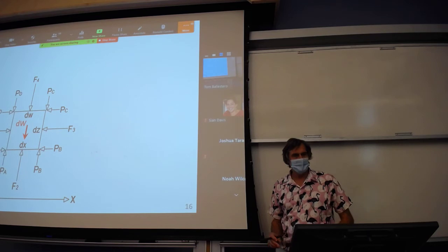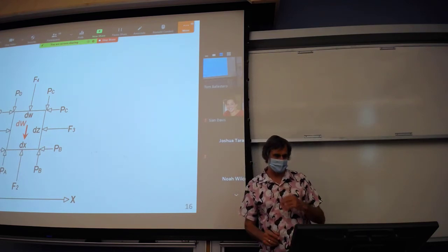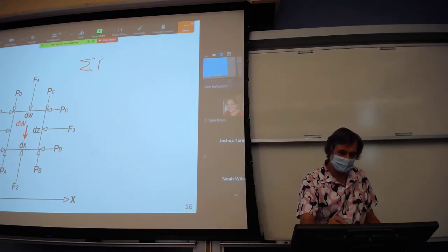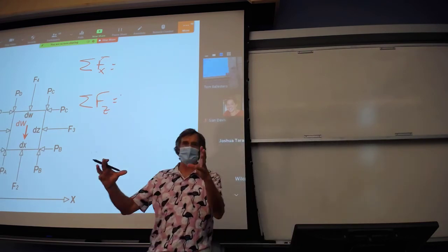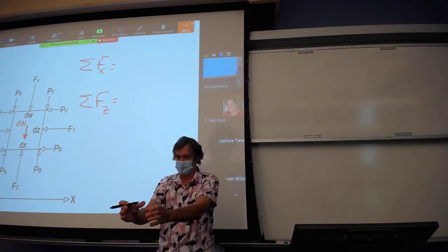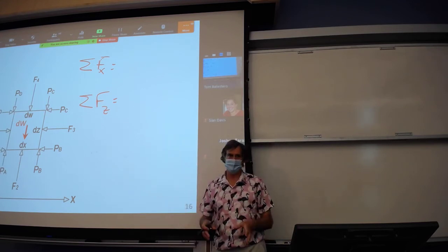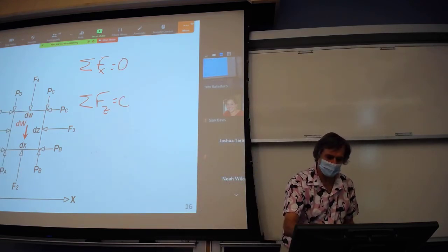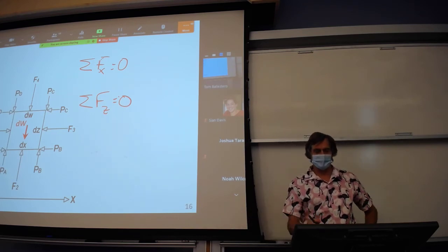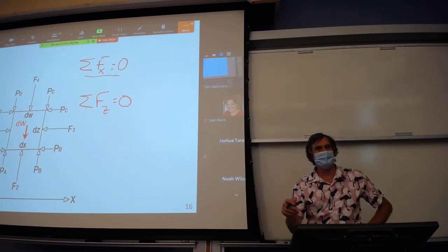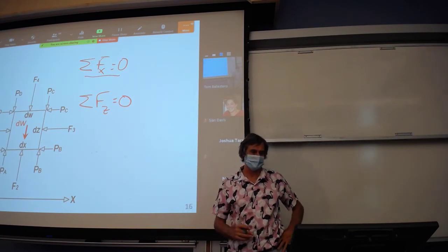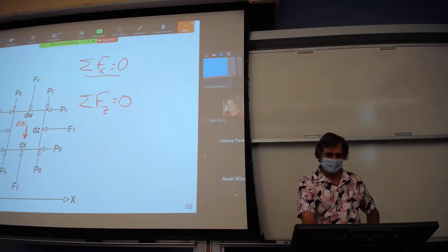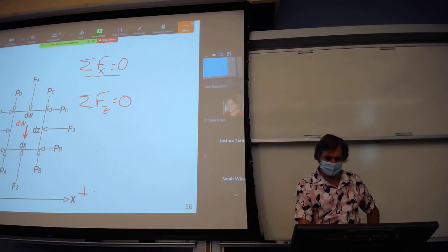And so again, what we're trying to do is a force balance. We can look at some of the forces in the x direction. We can look at some of the forces in the z direction. In that swimming pool or your bathtub, this element is just sitting there. It's static. And so in any direction, those forces should sum to be 0. And remember, we're just saying that y is going to do the same thing as x because gravity is only acting in the z. And so in this case, in the sum of the forces in the x direction, remember positive x is to the right.